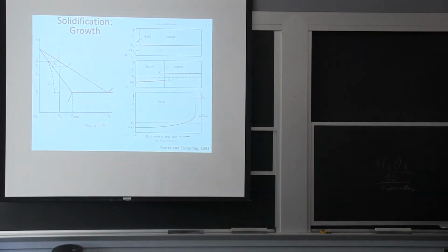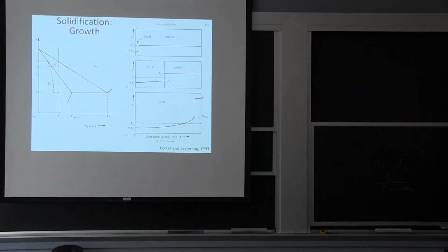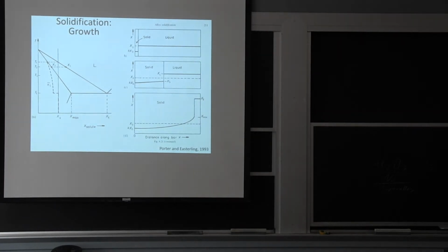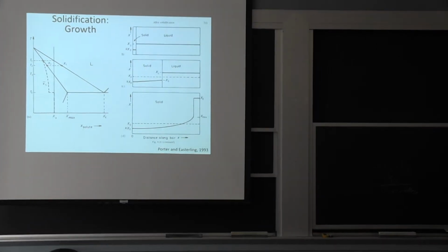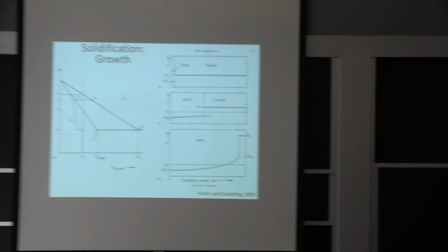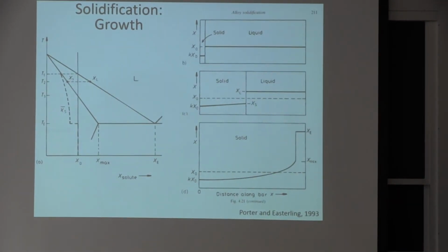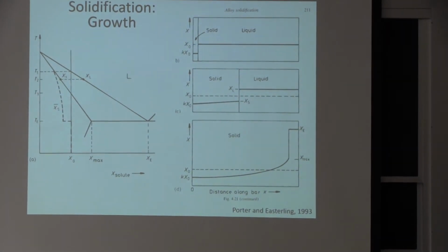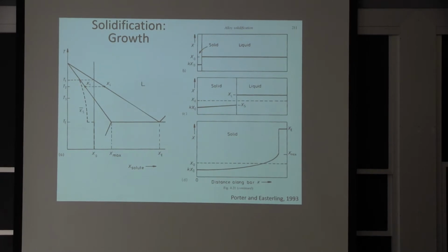The second topic, solidification: this idea that you're going to form dendrites a lot of times comes from this segregation of the alloys. When you try to solidify, a lot of times you make a pure first grain, and you're pushing away all the alloying element, and when you're done, that's where you get a different structure.